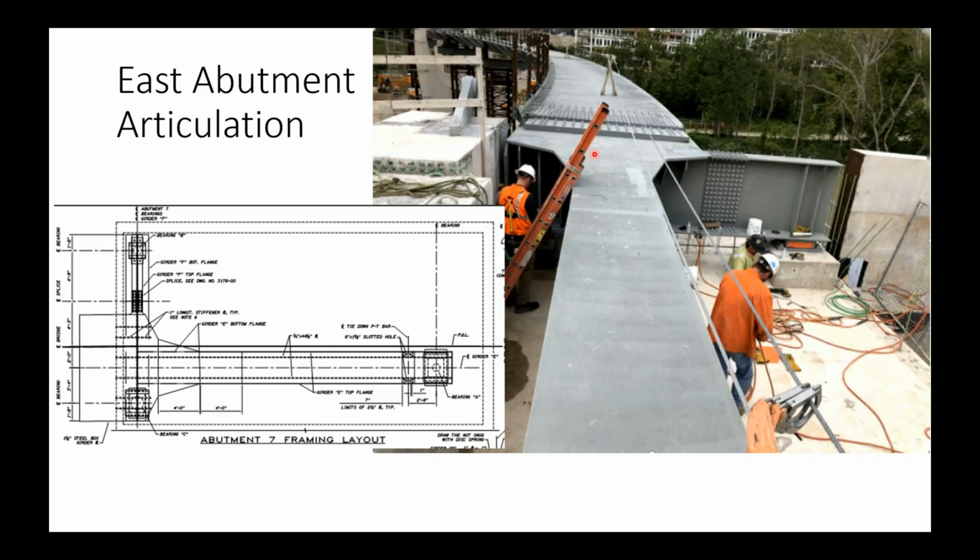If we have a pin support here, that's going to make this span of the deck quite a bit more flexible. So we wanted to really find a way that we could make this abutment act as if it were a fixed support. And the way we did that was we extended the primary girder an extra 30 feet back into the abutment. So that's this extension of the girder.